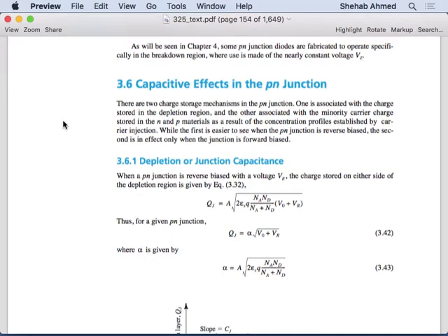You've made the barrier voltage very small, right? Meaning what? You've removed the bound charges in the depletion layer. They've recombined with carriers from both sides, right? That's what you did. You decreased the size of the depletion layer, right? And this is forward bias mode.